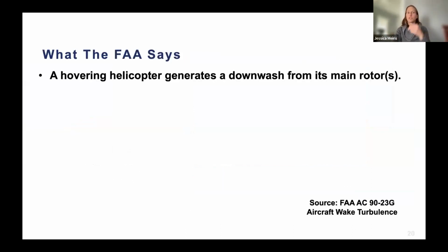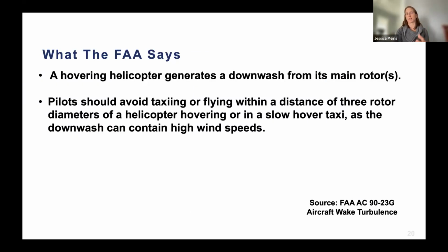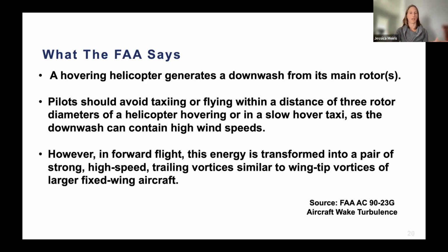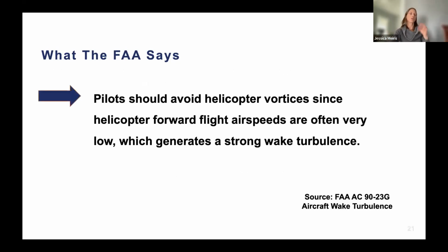What the FAA tells you about helicopter wake turbulence has a heavy focus on the hovering aspect of it. So hovering helicopter generates downwash. Yep, got it. However, there isn't very much focus on helicopter in moving forward flight. This is all it says. The energy is transformed into strong, high-speed trailing vortices, similar to wingtip vortices of fixed-wing aircraft. That's it. Doesn't really tell you what to do about it. So there's a heavy focus on the hovering aspect, but not a lot of information on what you can do in forward flight. So we're going to move in that direction.